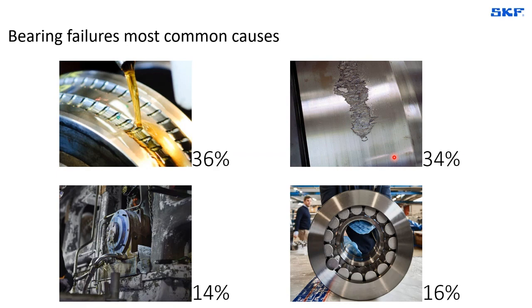We can say, for example, material fatigue, and material fatigue can be seen as a normal failure mode on which the bearing life and the bearing selection process is based, but it can also be a consequence of abnormal stress applied to the bearing due to things like misalignment or oval support surfaces like the shaft or the housing, excessive unbalance, excessive belt tensions, or even choosing the wrong bearing for the job.